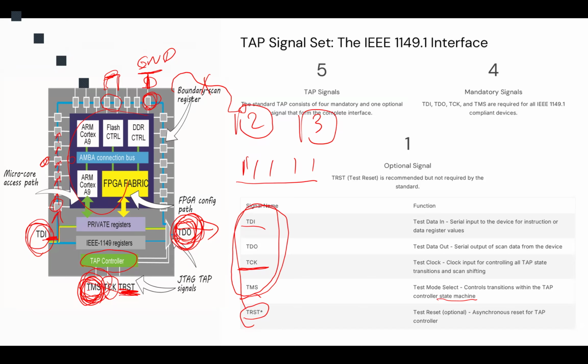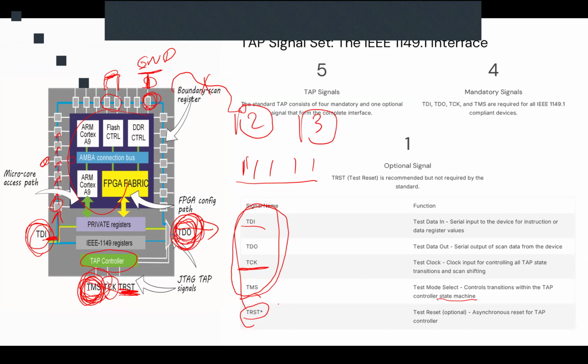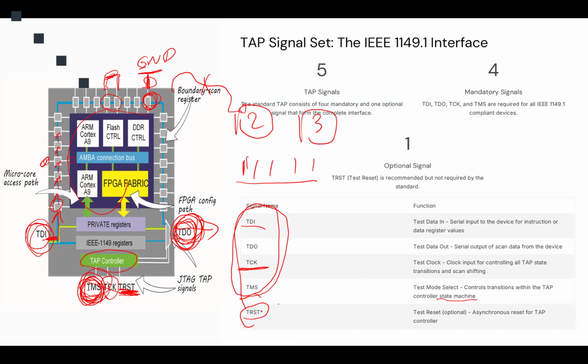It doesn't matter what type of chip or digital system you are designing. It could be an FPGA, it could be PLCs, it doesn't matter. The only optional choice that you have is that reset input. You can have it for easier resetting of the tap controller, or you can eliminate it and use 5 bits equal to one in a row in the TMS to reset the tap controller.